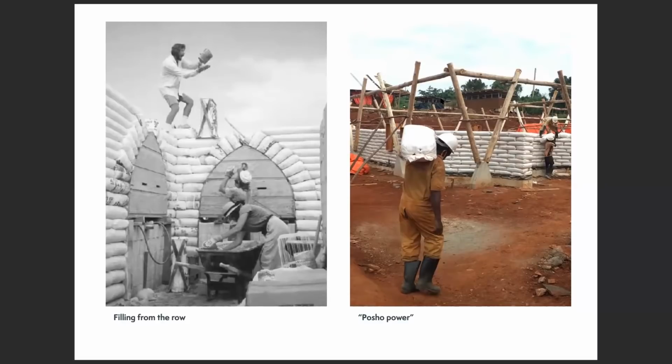All our bags were filled at a central location, where the stockpile was. We used buckets to measure, or more or less our frame, because as Edson has explained, it is very important that the amount of soil in every bag is very controlled, so that you get an even size of bag. Then they stitched these bags and carried them to the actual site, where they put them in place and compacted them. We shall see that in our practical exercise in a moment.